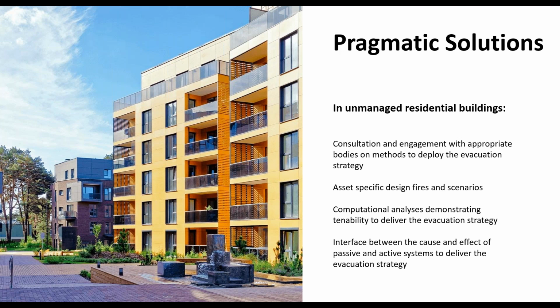Certainly a pragmatic and proactive design narrative that is supporting specific scenarios to assets, much in line with what we've been hearing about the use of high hazard approaches such as safety case principles in HRBs, and being very specific in fire strategy development about selection of design fires that help build out a narrative to justify why an evacuation strategy is appropriate in an unmanaged residential scenario.